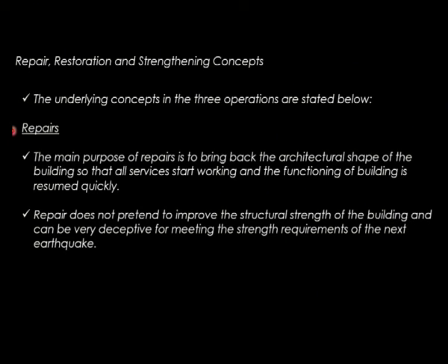So, moving on to the next major topic, that is repair, restoration and strengthening concepts. The underlying concepts in the three operations are: for repairs, the main purpose is to bring back the architectural shape of the building so that all services start working and the functioning of the building is resumed quickly. So, repair does not pretend to improve the structural strength of the building and can be very deceptive for meeting the strength requirements of the next earthquake.